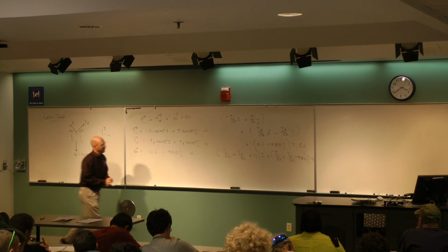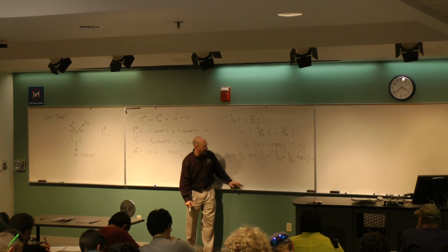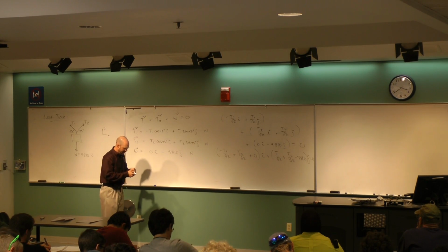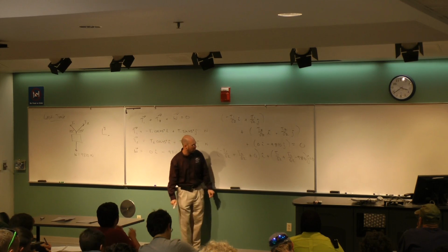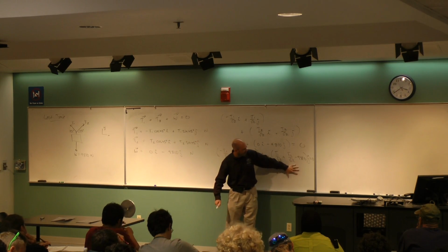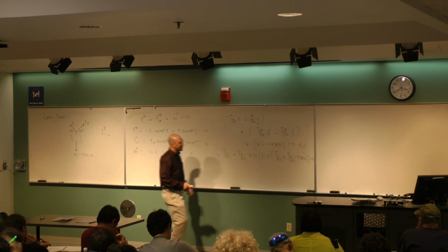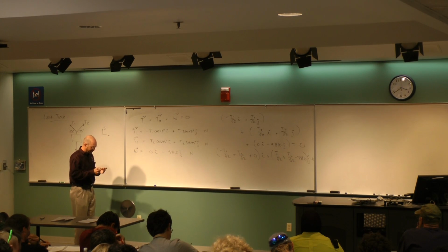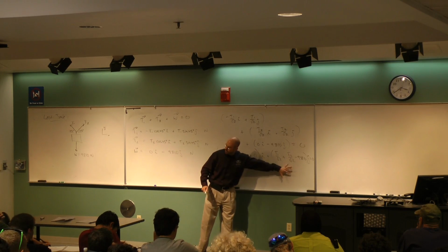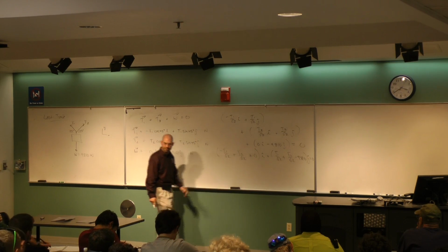At this point, when you solve a vector problem for static equilibrium, you should end up with a summation of terms that equals 0, where one term is something times i and another is something times j. If I add these up to get 0, what does that mean separately about what's in front of the i's and the j's?